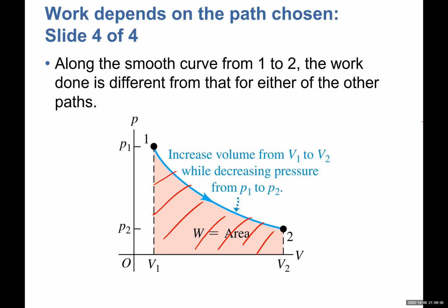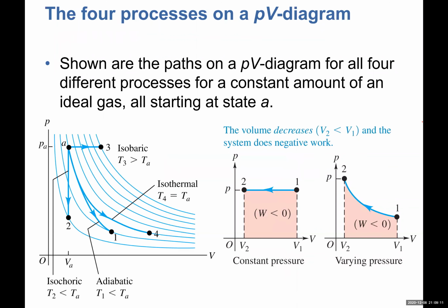All right. So I've been saying that we're going to be able to incorporate the temperature into our diagrams, and that's what we have. On the left side, you can see this PV diagram, and the blue lines actually represent temperature. The vertical line is the pressure, the horizontal line is the volume, and the blue lines are then the temperature. So the temperature is actually constant along that blue line.